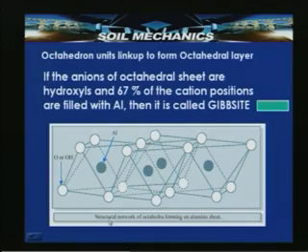But several clay minerals form with combinations of silicate and gibbsite sheets only. The figure below shows the structural network of octahedra forming an alumina sheet, with different octahedron units linking up to form an octahedral layer, a gibbsite layer or alumina layer, as can be seen here.